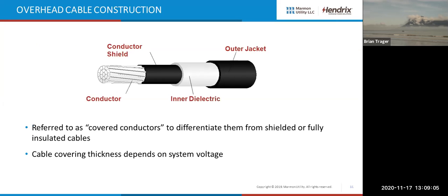We've got a 3-layer insulation system. The semicon shield is there for the same reason we use a semicon shield in underground cable. We essentially want to fill in on top of the individual strands, which may have mechanical sharp objects on them, and we also want to fill the interstices between those individual phases.